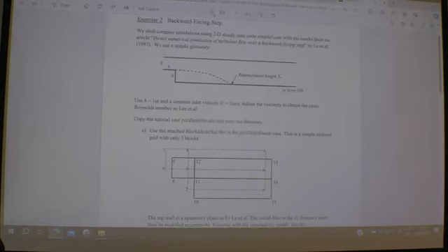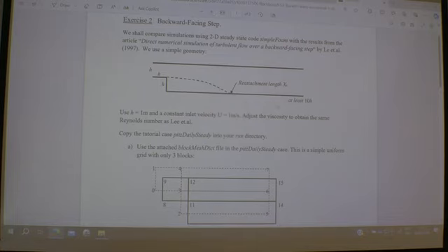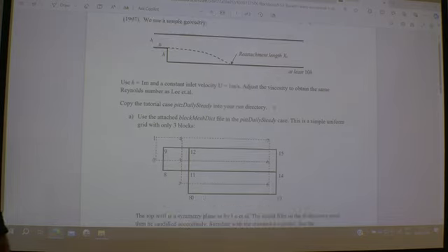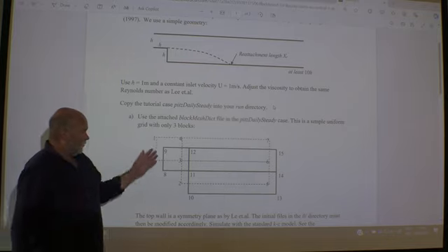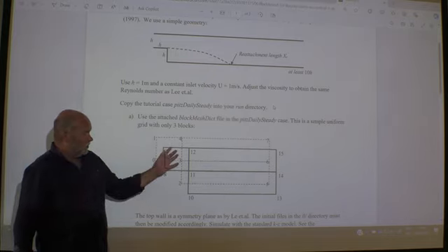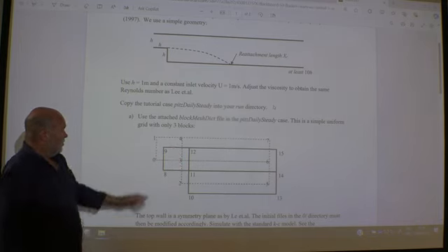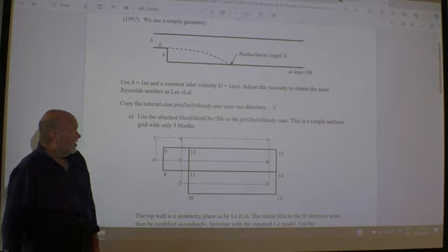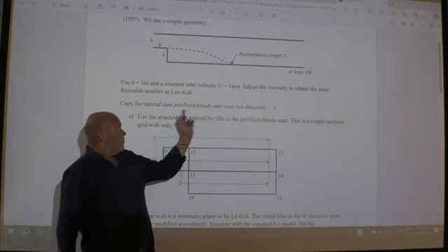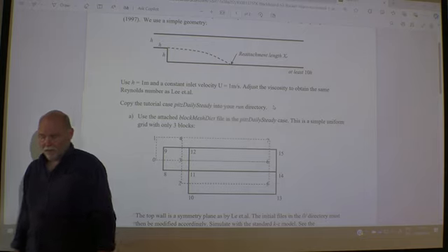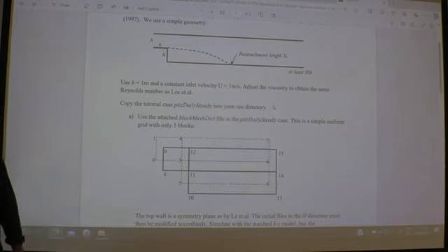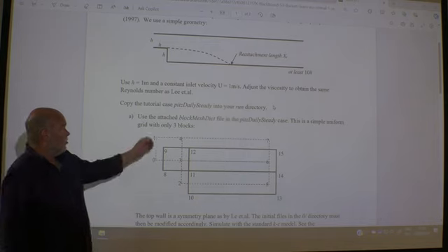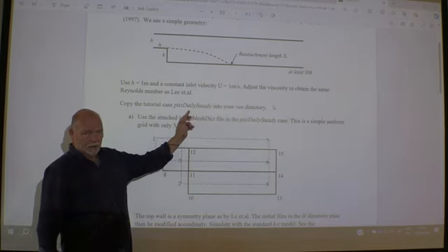You have then been given a blockMeshDict file. So you don't have to punch that one in for yourself. I just made it very, very simple, 3 different blocks. So use that one and use the pitzDaily steady case. Now, depending on your version, your distribution of OpenFOAM, it may be called only pitzDaily or pitzDailySteady.